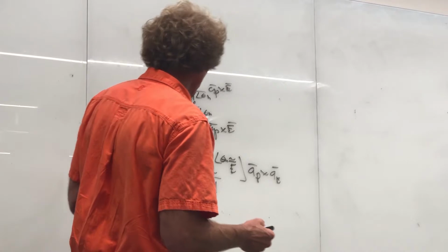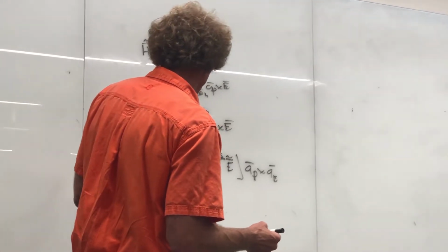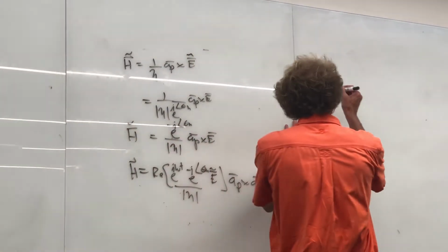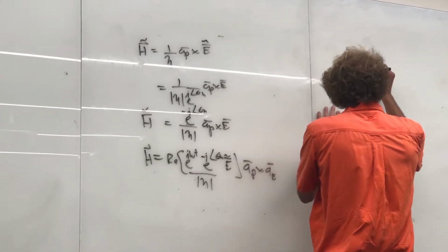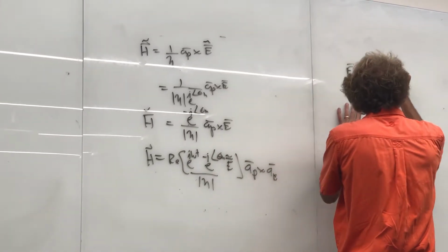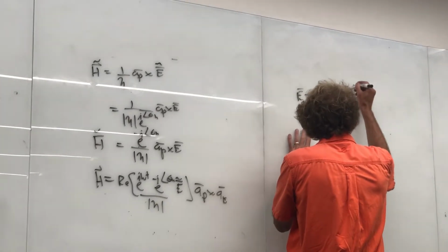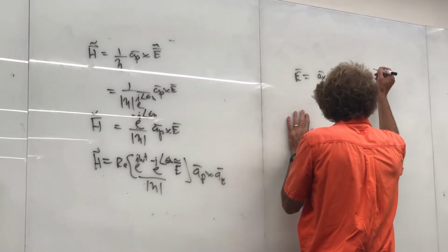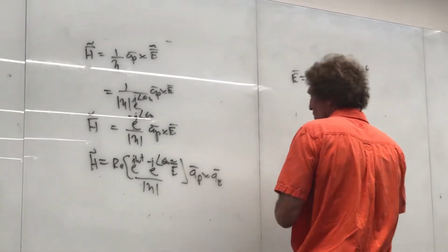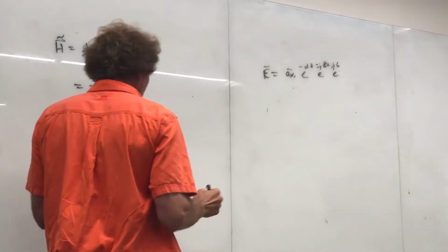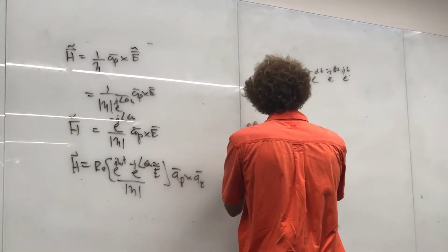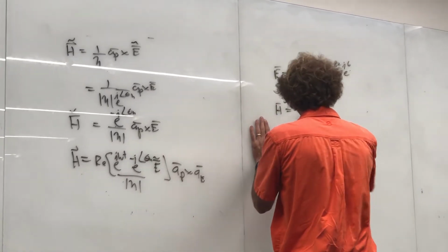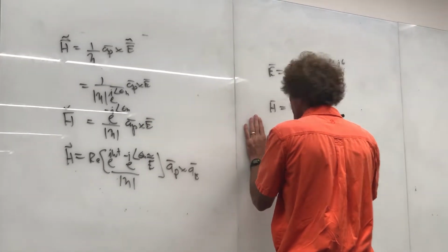Now the E field in general, you have to have an equation for it to get the H field. But for the E field, normally it would be something like, in the A x direction, e to the minus alpha z, e to the minus j beta z, and there may be a phase angle here. But for now, if there was e to the, say, j theta right here, well, when I put that in here, I'll just do the whole thing for you. Now, if I put the H field in here, I get the real part of 1 over the magnitude of eta, and then I get,